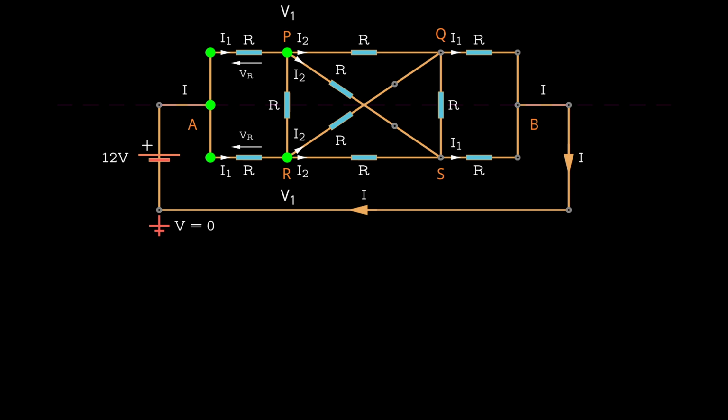We now have two options: either remove the resistor from the circuit, or connect the two nodes with a conductor. Connecting the nodes will make it easier to further simplify the circuit. At this point, we have 4 resistors left to deal with. The circuit remains symmetrical about the axis between nodes A and B.